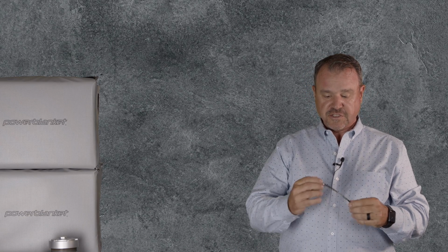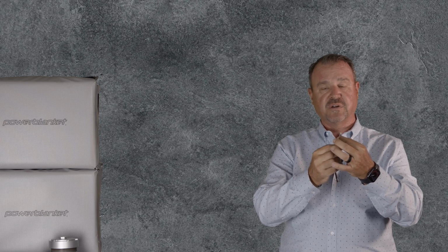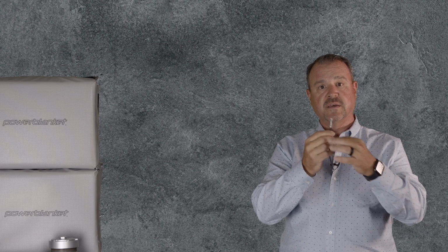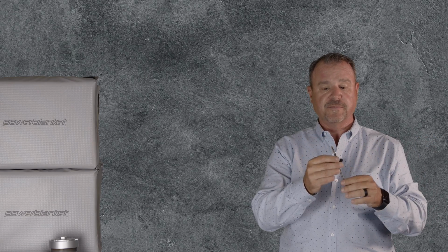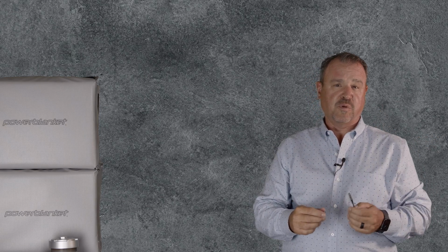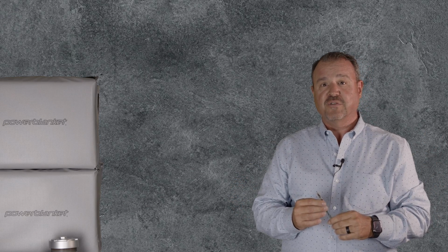On-off temperature controllers are the most common type of temperature controller out there. Good and reliable, rugged. As a matter of fact, this sensor is the one we use in every single ready-to-ship power blanket that goes out the door here at Power Blanket. These controllers are made up of a device inside that can sense temperature, and then it can open and close a relay to allow power to flow to a heater or to turn a heater off and on. These controllers are very reliable. You can think about maybe the last time you ever replaced a sensor in your oven at home.